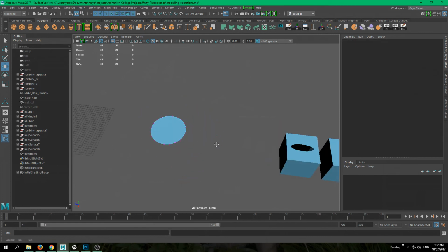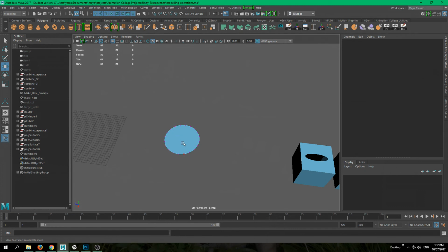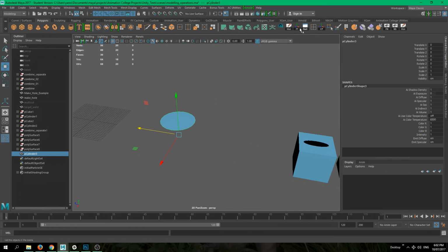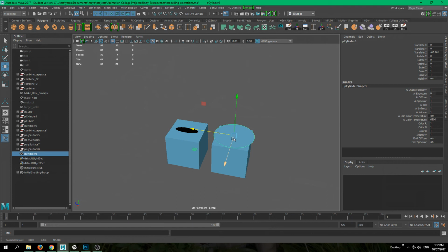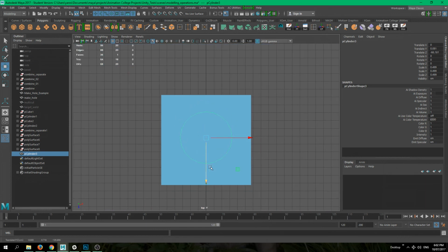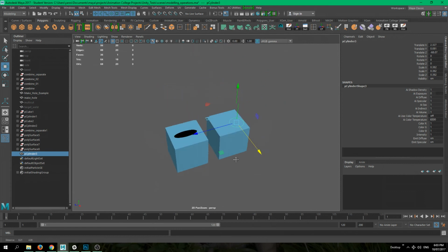Cool. So instead of getting rid of the edges, I just got rid of the middle vertex. Now we have this one continuous face. I can also center my pivot point for this one. Now I can drag this object over. And let's say I will position it somewhere around here. Maybe around here. I can look from the top view as well. So maybe we'll just position it like so, and go back to our perspective mode.